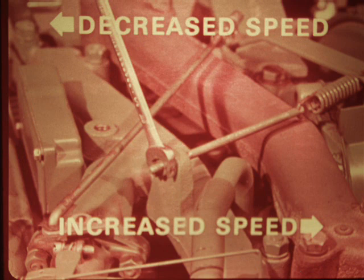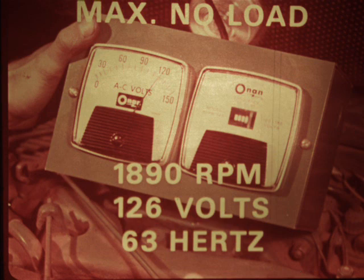Set the no-load speed at the governor spring adjusting nut. Loosen it to decrease speed or tighten it to increase speed. Adjust the nut for 63 Hertz on the frequency meter. The maximum no-load speed is 1,890 RPM, and the maximum no-load voltage is 126 volts. However, the frequency setting will be most accurate for proper generator output and is preferred to RPM or volts.